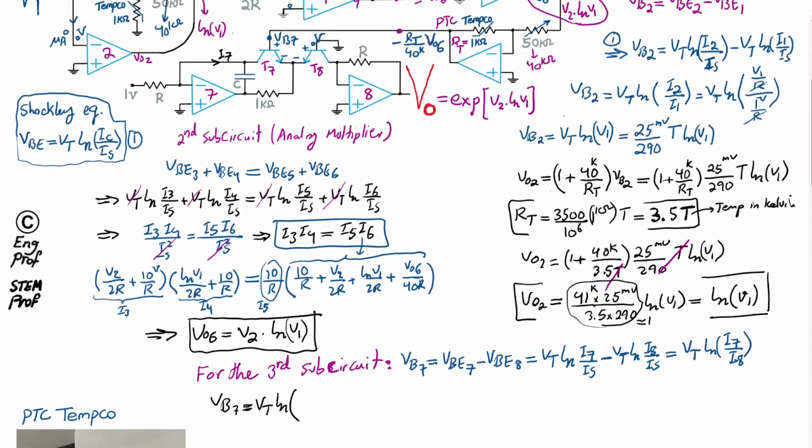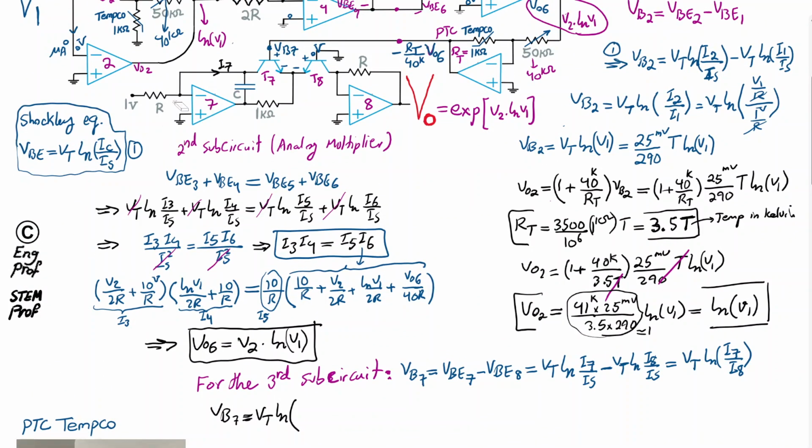So with that said, I7, again coming from this way, because of this op-amp in linear operation, we have 0 volt on the positive terminal. Because of virtual short, we have virtual ground on the negative terminal, and therefore we have 0 volt here. It means that the current I7 is simply the current that is coming through resistor R, which is just 1 volt divided by resistor R, because there is only 1 volt drop across that resistor. So 1 volt divided by R. That's I7. What about the I8?